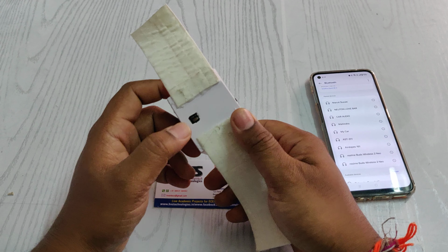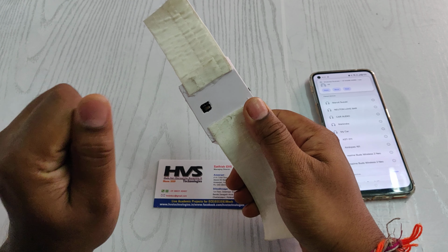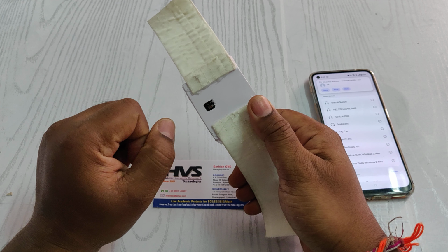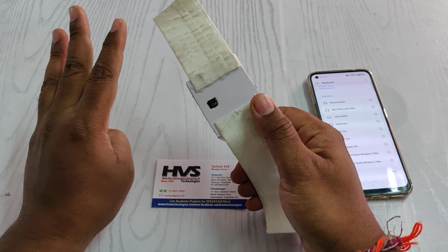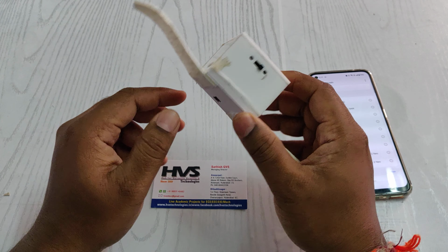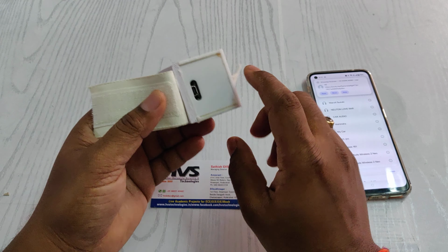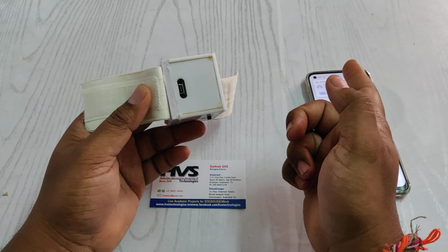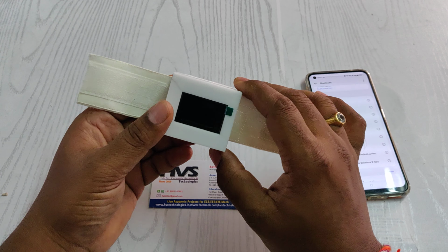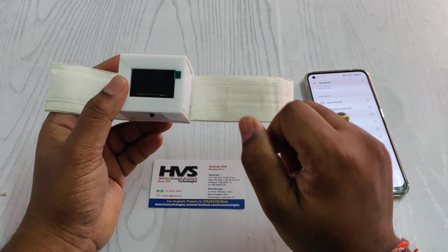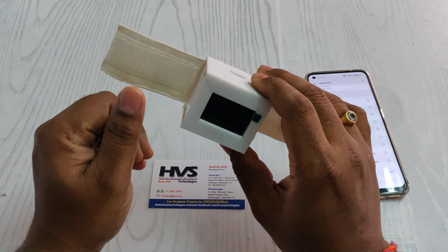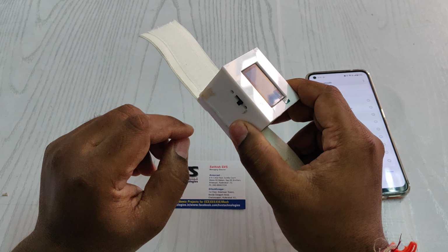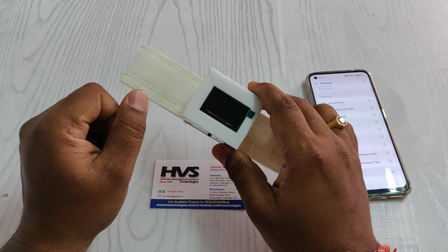It has a sensor with an IR sensor, red LED, and photodiode, along with green intensity, not the green LED, green intensity. In total we get 3 parameters. If you want to check the parameters directly, we can access the data from this USB cable to the Arduino serial port. There we directly get the IR data along with the red LED and the green intensity of the lights. So these 3 parameters are the main input to the system.